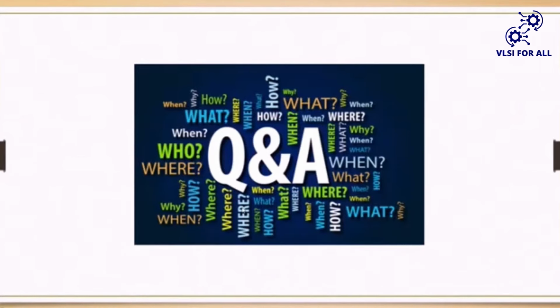So if you ask me what are the input files required for logic synthesis, I say simply tool license, RTL code, .lib file, .sdc file. That's it. Whereas for physical synthesis, I require tool licenses, RTL code, .lib files, .sdc files, LEF files, and the DEF file as well. So what is a DEF file?